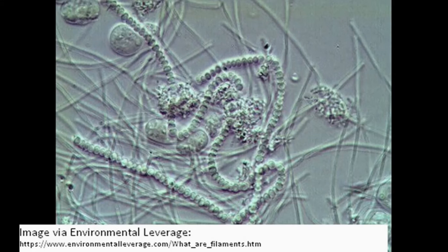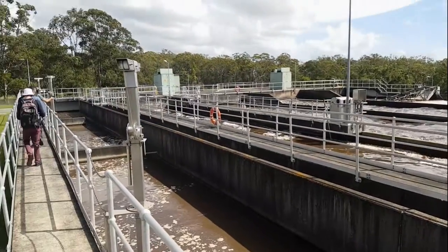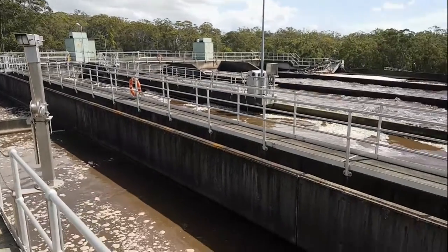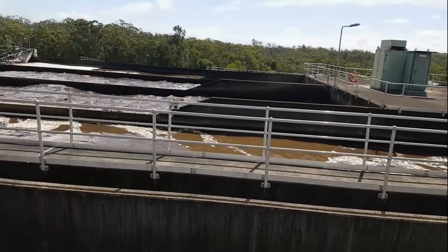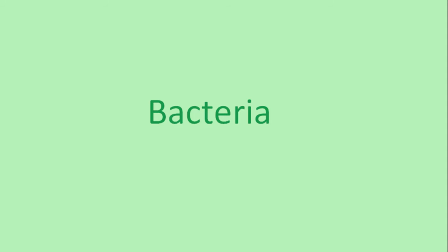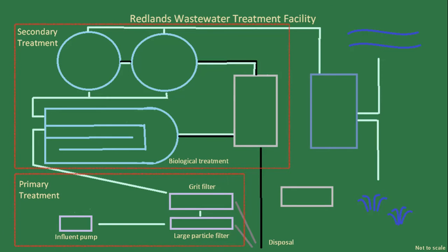The biological treatment process was explained to me by likening it to a bug farm, and this is helpful imagery to understand it. By caring for our bug farm, we ensure that they stay healthy and produce desirable results for us. The ecosystem is composed mostly of bacteria, but it also includes protozoa, fungi, and nematodes living in a managed environment where they can thrive. Influent is pumped from primary treatment into the aerobic zone.